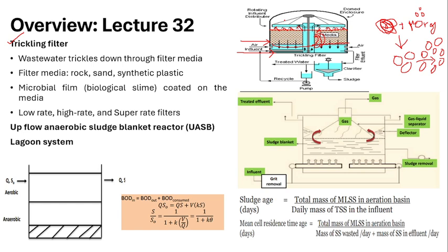So that is the falling off of the organic material utilized by the microorganism. Okay. So now the filtered water will be collected in this clarifier tank. So whatever sludge is produced, after sloughing there will be a falling off of the sludge. Those are collected from this clarifying tank, and the clarified water present on the top will be collected as the treated water, and then it can be treated again by recycling it, or it can also be passed to